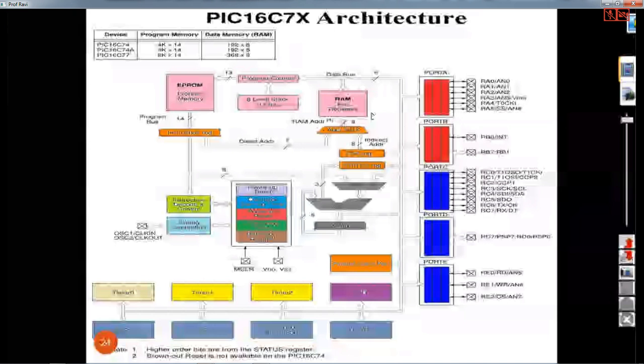And the same thing now in detail, you try to see the 16F877 architecture. At the CPU block diagram level, you have the CPU and the program memory, with 13 bits of program address. 13 bits, so 2 power 13, which is 2 power 3 times 2 power 10. So 2 power 3 is how much? 8 kilobytes. So 8 kilobytes of program memory.